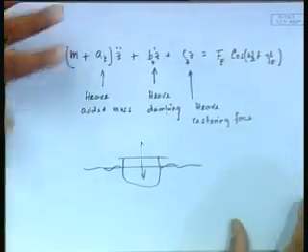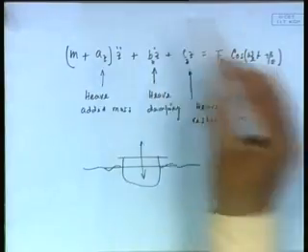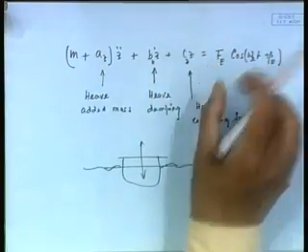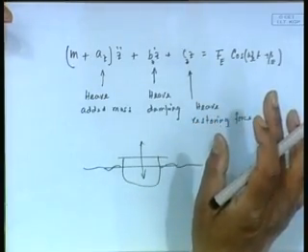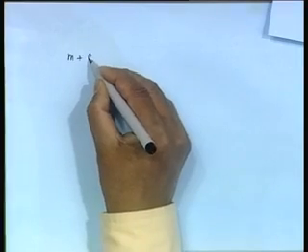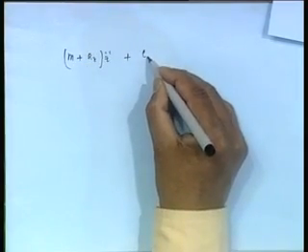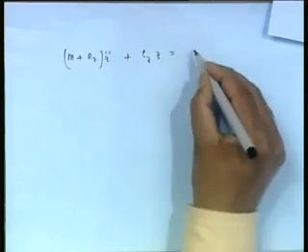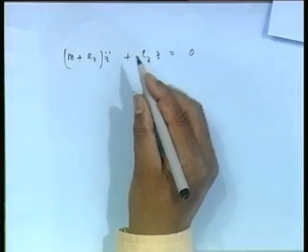Now, this equation of motion looks like a vibration equation. If I made the forcing 0 and removed damping, what I end up getting is what is known as the undamped natural motion, or the equation for free undamped motion. So, let us look at that. If I just consider the inertia force and Cz z equal to 0, then this is my so-called undamped free motion.